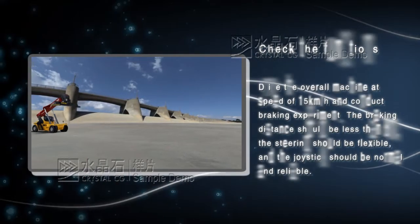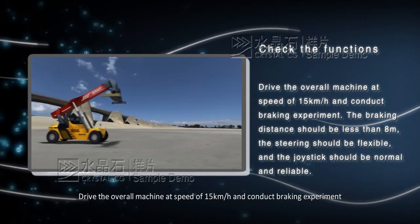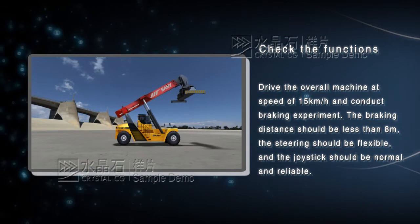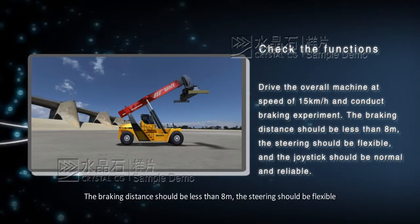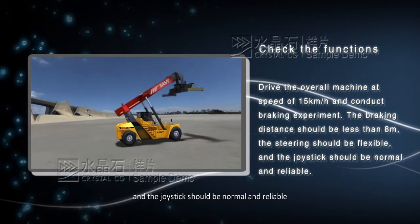Check the functions. Drive the overall machine at speed of 15 km/h and conduct braking experiment. The braking distance should be less than 8 meters. The steering should be flexible, and the joystick should be normal and reliable.